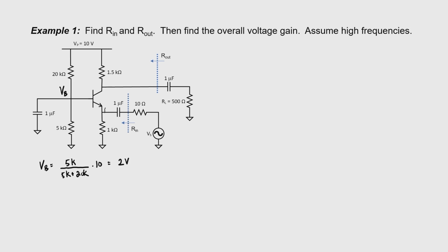And what you want, in addition to that, is where the signals are amplified, you have a lot of room to swing around. So in order to make sure that the transistor doesn't saturate when the collector swings low, you want the voltage here at the collector to be somewhere midway between the power supply and ground. You don't want this voltage to be too low. You want the low voltages down here. That's what we've arranged. Assuming we have a forward bias diode, then we should have about 0.7 volts drop down to the emitter.